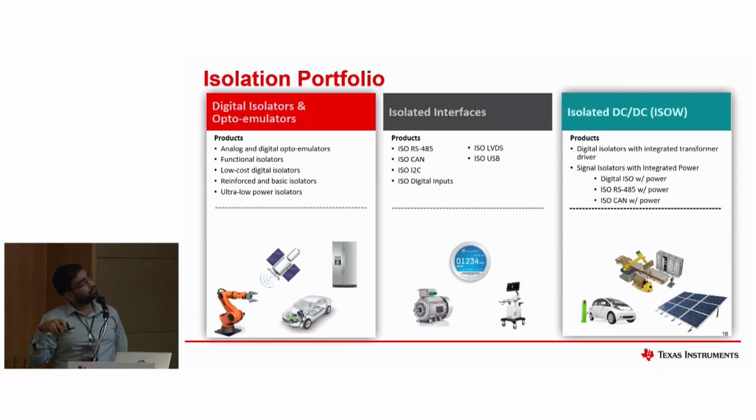Generally these devices can provide load currents of around 120, 130 milliamps. But if you have a higher requirement than that, then you need to use a secondary transformer outside the device, which can suffice your load requirement.